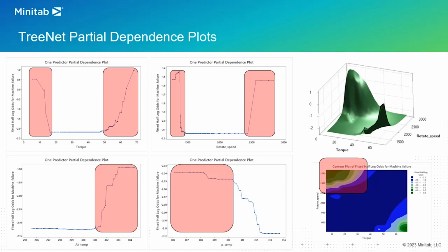That basically means that the turbine is spinning out of control, and the centrifugal forces can produce the associated failure of that machine, right? Or just some natural friction within the shaft. On the other hand, another area of danger would be the area that has a high torque and low rotation speed, which means that the grid overloads the turbine, and it's becoming progressively harder and harder to rotate it and to move the blades, and ultimately that can create an internal rise in temperature and all these other things.